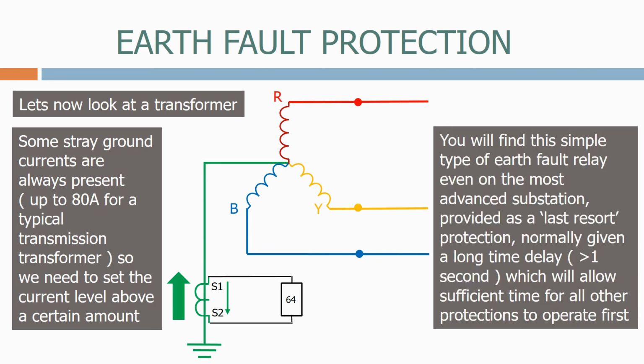You will find this simple type of earth fault relay even on the most advanced substation, provided as a last resort protection, normally given a long time delay greater than 1 second, which will allow sufficient time for all other protections to operate first.